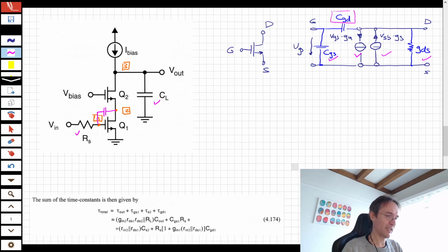So the idea which I have now is to simply say what happens if the gate drain capacitance of the transistor number 1 is 0. And then I see when I do that, here the Y1 is suddenly occurring in all of the terms of the denominator, so I can actually factor it out. Yes. So let's do that.